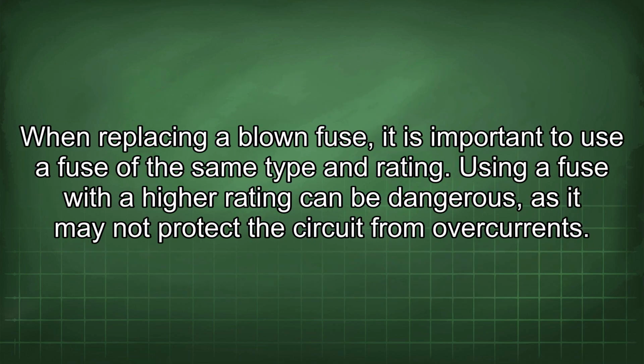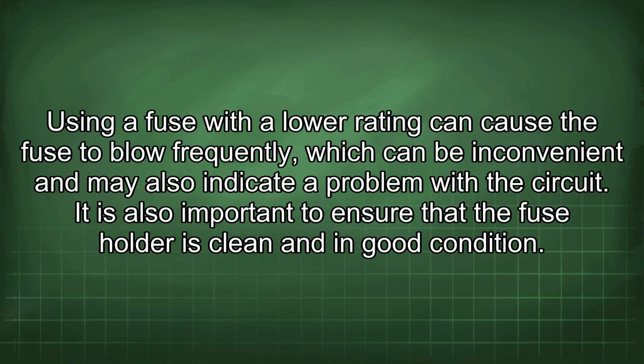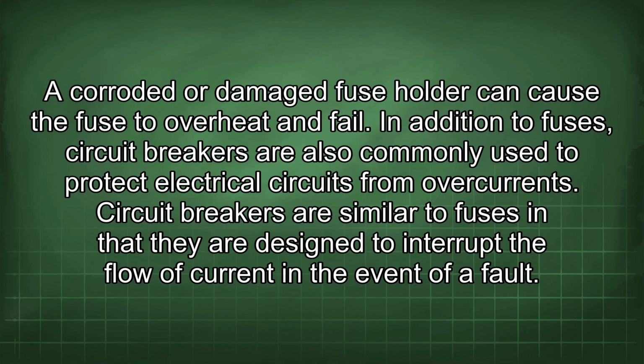When replacing a blown fuse, it is important to use a fuse of the same type and rating. Using a fuse with a higher rating can be dangerous, as it may not protect the circuit from overcurrents. Using a fuse with a lower rating can cause the fuse to blow frequently, which can be inconvenient and may also indicate a problem with the circuit. It is also important to ensure that the fuse holder is clean and in good condition. A corroded or damaged fuse holder can cause the fuse to overheat and fail.